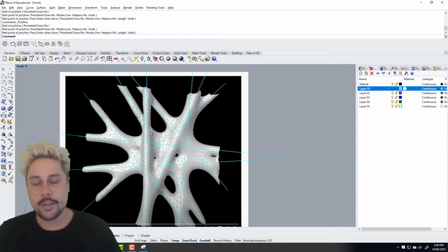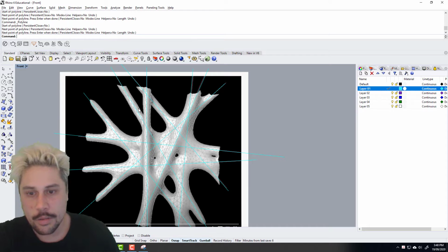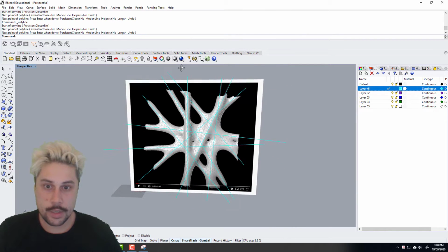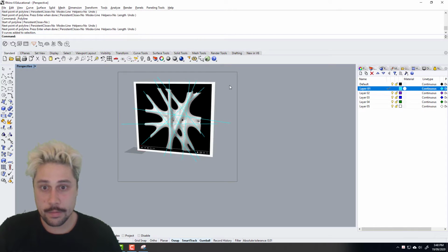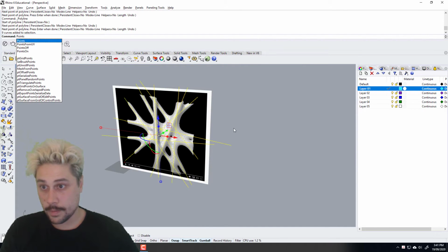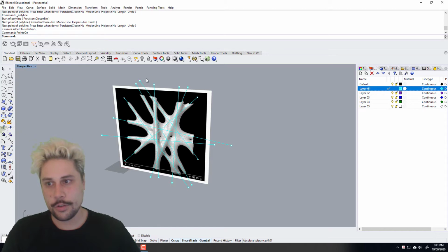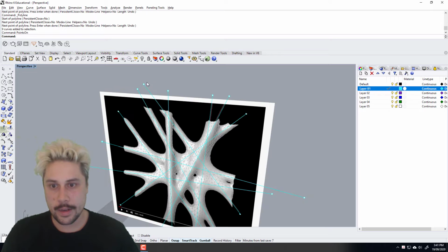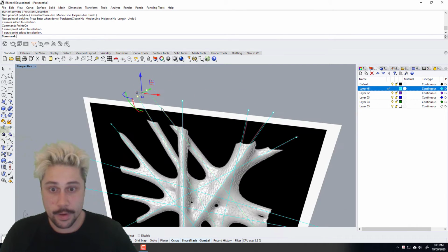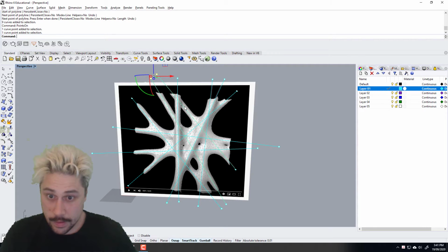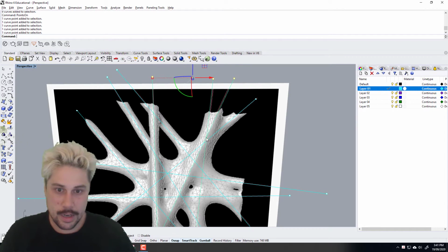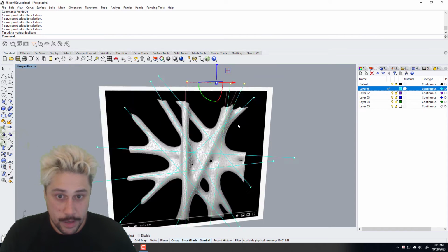You'll see that there looks like there's a bit of depth to some of these curves. So I'm just going to go into perspective mode now and tweak them slightly by turning points on, like so. Because they're just lines, I'd use the polyline command, they're only going to have 2 points. I'm just going to grab a couple that are on the same plane. It looks like this one's out in front of everything, as does it for these two. This one looks like it's kind of in the back. I'm just going to shift that over like so.